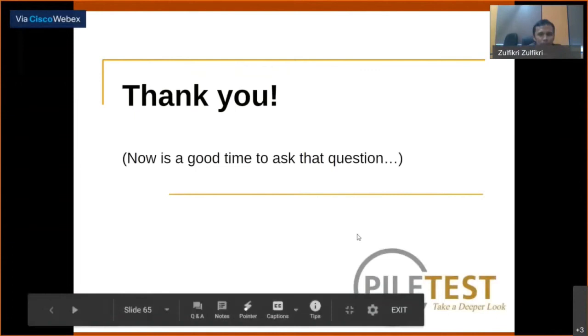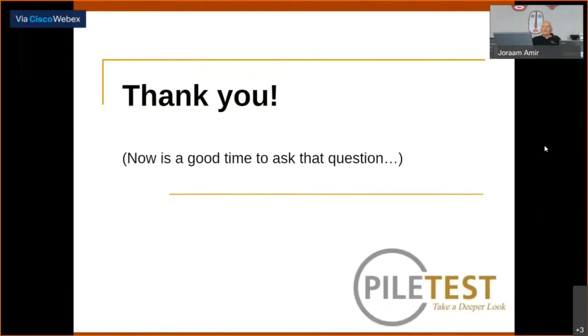There is a question, I think I covered it in my presentation: what's the difference between flaws and defects? A flaw is any change in the composition or in the form of the pile, any one, large or small. A defect is a flaw that affects the performance of the pile, so it's a special case of a flaw. A defect calls for action on the side of the engineer. They have to do something about the defect.